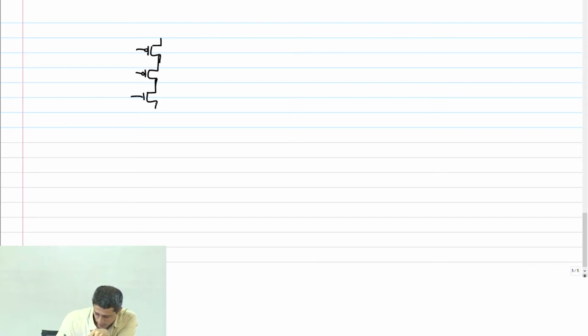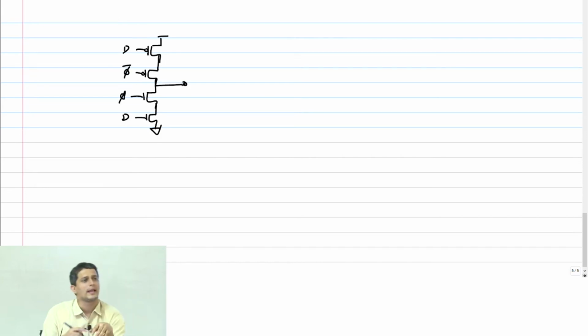So now let us look at this connection, right? I said a tri-state inverter had to be like this. This is D, phi, phi bar. Can I swap D and phi? Logically, this is also a valid flop, right?